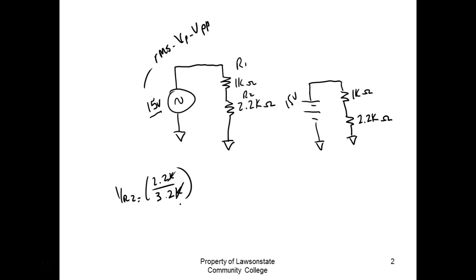So we're going to use the voltage divider formula a lot in this class, because most of the time you can do RT in your head, especially when you're only dealing with 2 resistors, right? You understand? And you can calculate the voltage drop without calculating what? Current. So it saves you a formula. And every formula you can save is going to be a lesser chance for you to make a what? A mistake.